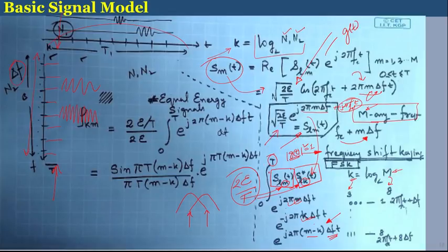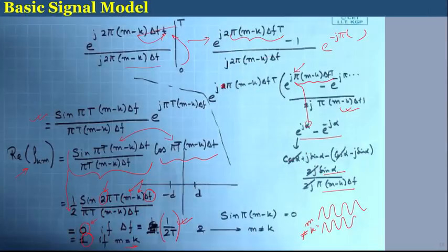So, that means we are as if saying that one particular signal is sent out of the different frequencies, and at the receiver you are correlating with some other signal as a result of the typical matched filter operation. So, if this signal is not the same as the original signal, that is, if it is not matched to the signal, then what we get is a 0, right.